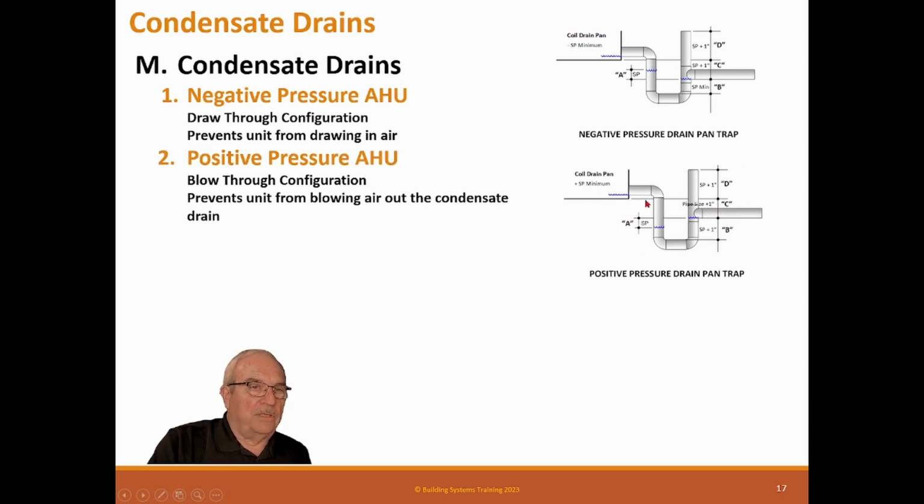Because now we don't want this pushing the water out of the trap. Because once there's no water in the trap, then it's no use. It's not a trap anymore. And I know if you guys have ever bought a package unit and the factory ships you a little bent piece of plastic, totally worthless. It's not going to do anything. It'd be just as good to not have anything of that. So traps are so simple, but still, as a commissioner, they were wrong on every job.